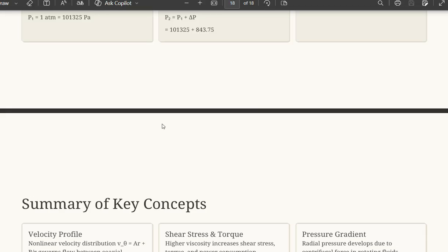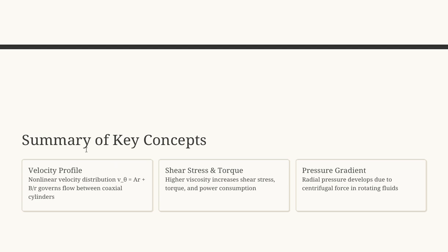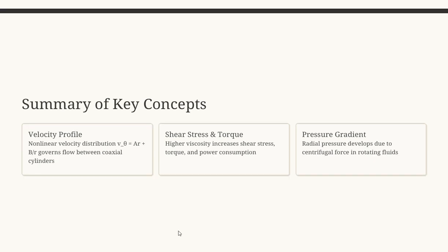Now to conclude, the velocity profile is non-linear. Shear stress depends on viscosity, and the rotation creates a pressure gradient, and this system is important in viscometers. Thank you.